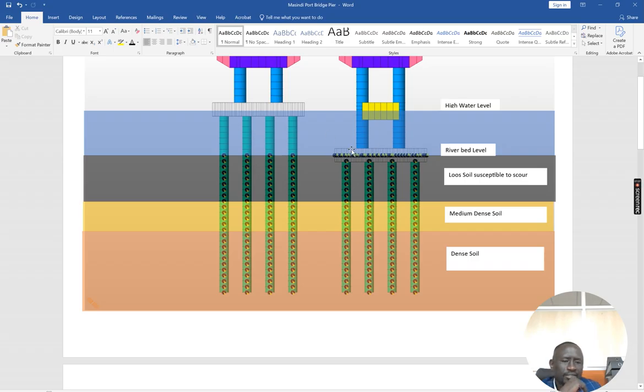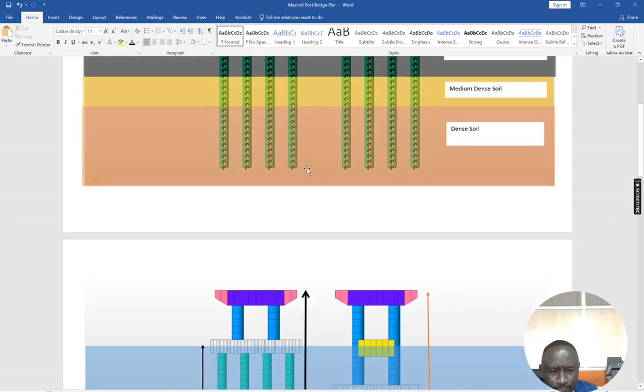this liquefiable, this porridge-like state of soil. That happens. Therefore, it leaves us to have effective depth with a bit of good rock, or even fair to good rock, to anchor your structure up to sound, so that you avoid the soil condition which changes to porridge-like during earthquake or tremor. So that definitely would also disqualify and also create a bit of instability condition. So normally it's avoided in your analysis.